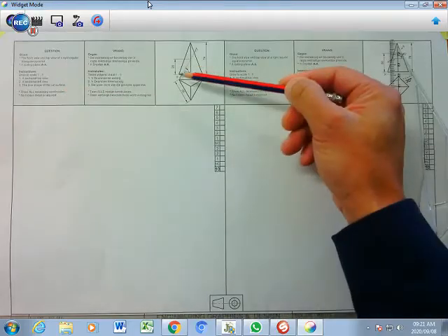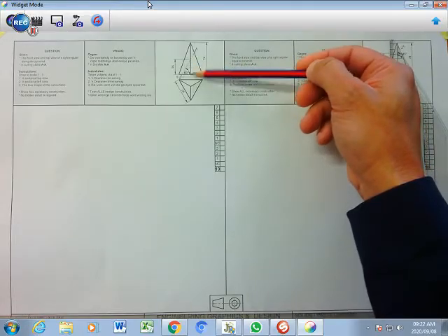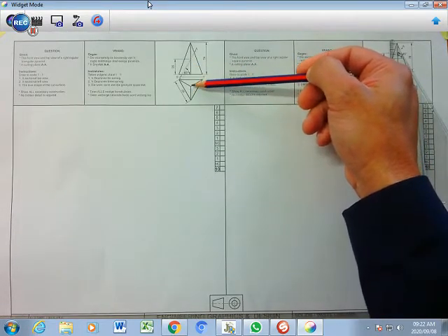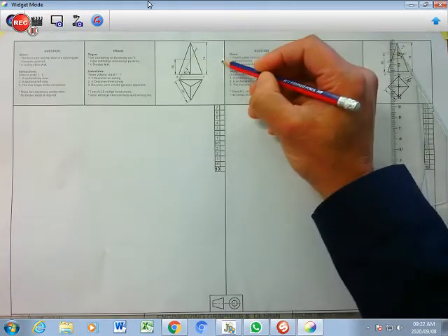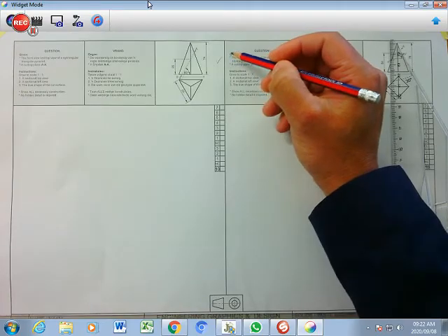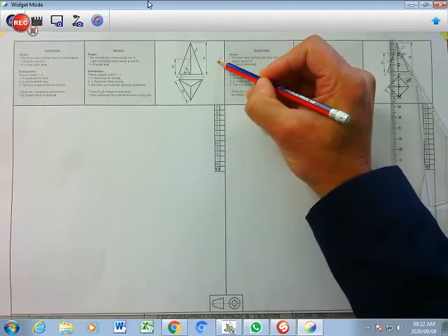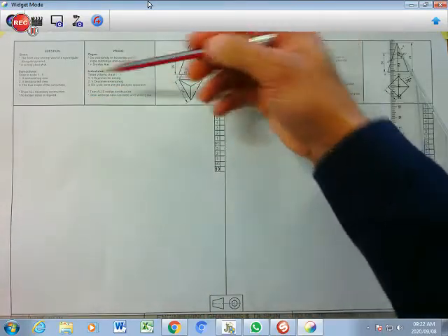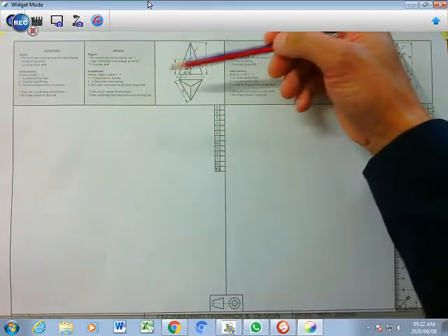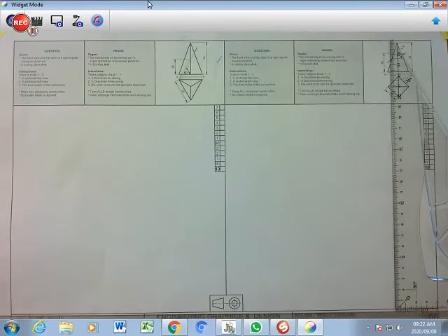What's the instruction? You must draw to scale 1:1. You can redraw all of that, and you're going to show the top view and the front view. The top view is going to be a section, and you're going to draw a left view as well on your right hand side, which is going to be here. So you've got to start more or less here so that you have your right view here, and then you must also draw the true shape of the surface which has been cut. You need to show all the construction, and no hidden detail is basically required.